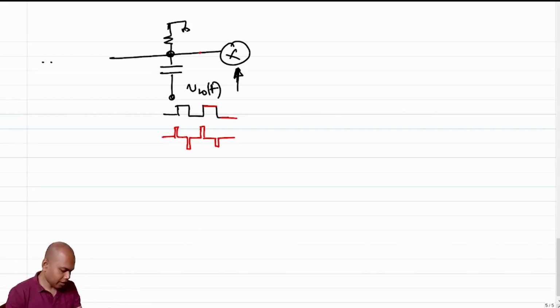So let's get that out of the way. So now let's find out. Now note that this is a periodic signal, right? Because the clock is periodic, the feed through, the leakage, will also be periodic. And let's assume that this leakage maximum is Vp, which can be 1 volt based on whatever we had assumed earlier. So what is the strength of the fundamental tone, because that is of interest, right?